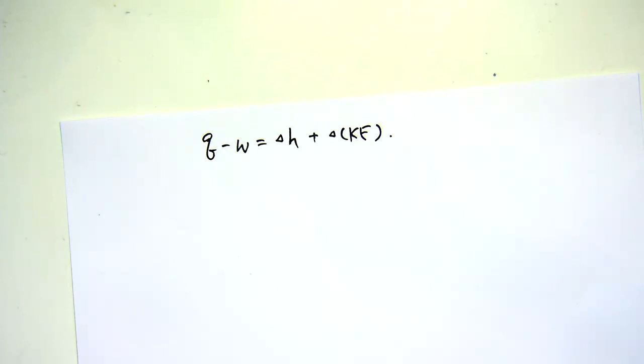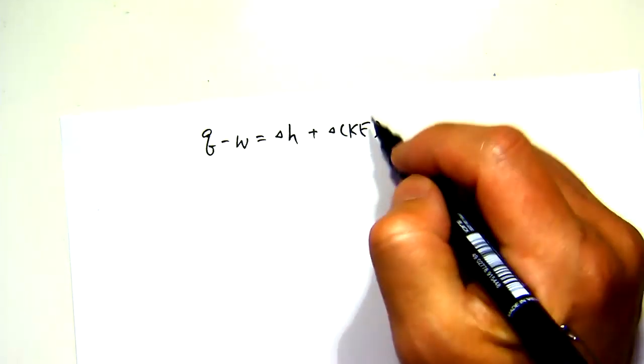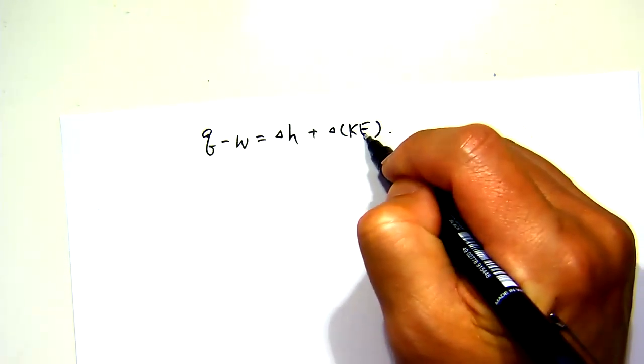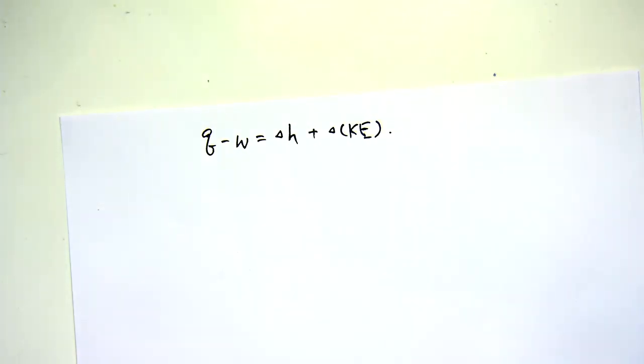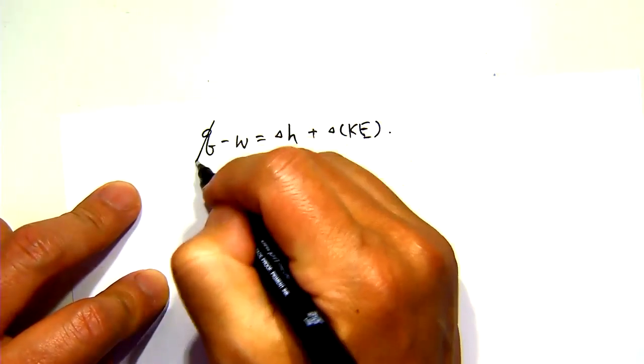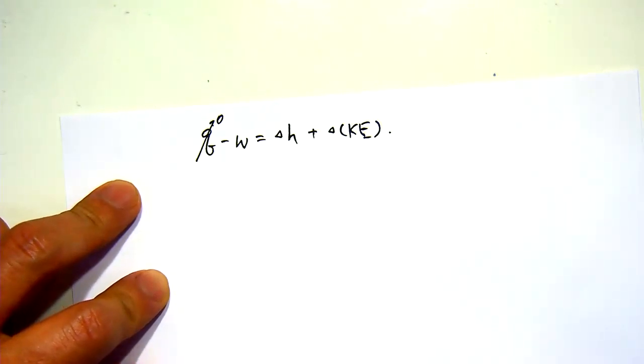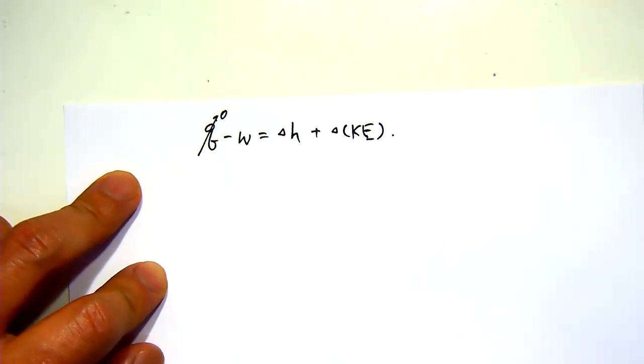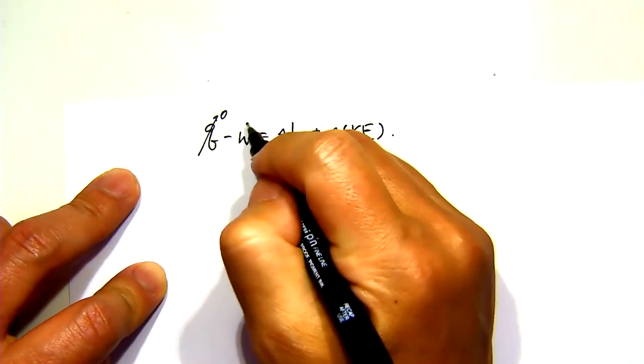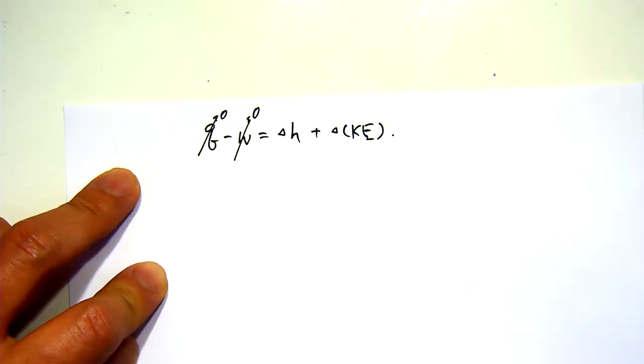Again, when we're dealing with stagnation property, the speed or the associated kinetic energy is not something you can ignore. You always consider the kinetic energy. This process, as I said, is isentropic, so this Q goes to 0, and this process does not do any work. No outside work being done to the system and no output work from the system. So both of these go to 0.